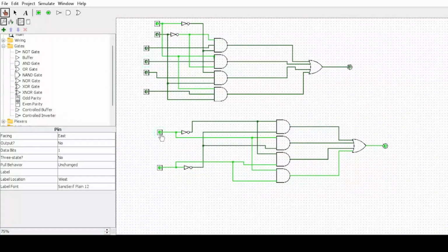So we are using this as a selector to select which kind of data we want. Let's say if here was 00, we are telling that this one should go. If it was 10, we are telling that this one should go. If it's 11, we are telling that this one should go. The selectors here behave like the selectors of the multiplexers, and they show what the output should be. So here the output is 11. You get me? Then 00. This one will go as the output.